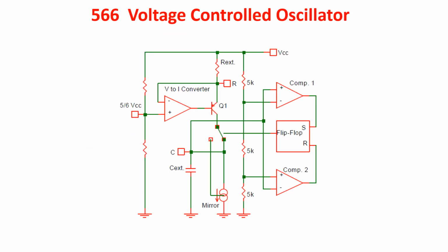According to Camenzind, the idea for the new IC came from the work he did at Signetics on the phase-locked loop. He had needed an oscillator whose frequency could be set by an external resistor and a capacitor and was not affected by changes in either supply voltage or temperature. Several products resulted from the basic design, among them the 566 voltage-controlled oscillator. What he first proposed to Signetics was this circuit, modified so it could also be triggered and produce a single cycle only, i.e. it would be both an oscillator and a timer.